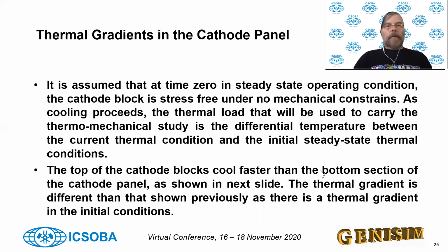So now for this mechanical modeling I'm going to present next, I need to have some assumption. And my assumption will be that at operating temperature, in operation, there's no strain and no stress. And from the cooling down, the strain will come from the decreasing of temperature.